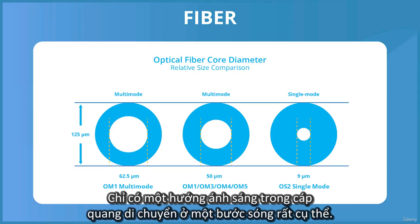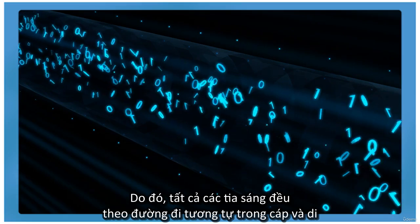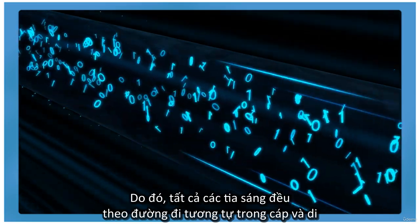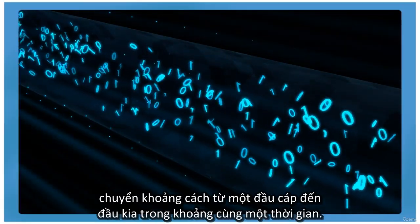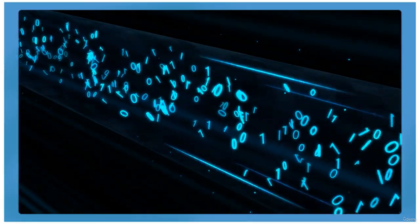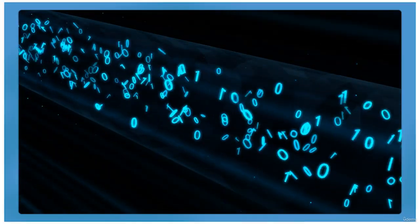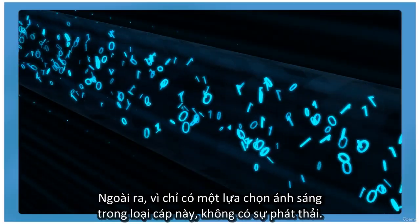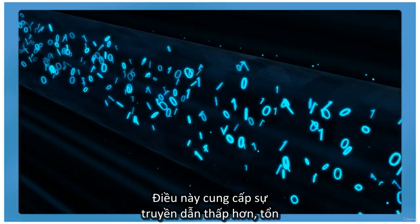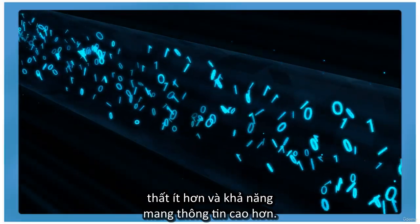There is only one light direction in the fiber that travels at a very specific wavelength. Therefore, all light rays follow approximately the same path in the cable and travel the distance from one end of the cable to the other in approximately the same time. This is one of the most important advantages of single-mode cables. In addition, since there is only one light path in this cable type, there is no dispersion. This provides less propagation loss and more information carrying capacity.